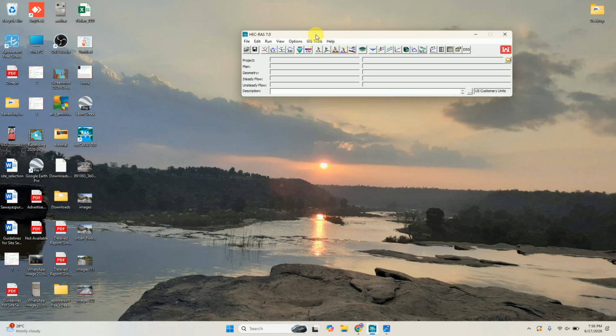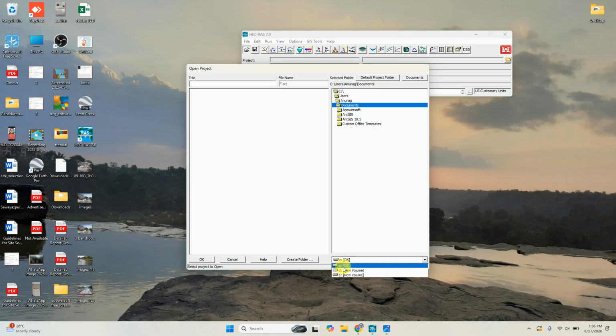Before 6.7, you will not find this feature in HEC-RAS, but currently, after 6.7, it supports the pipe or stormwater network. HEC-RAS allows you to model the urban system with a stormwater network as well. In 7.0, it is more convenient and more flexible to use the pipe network. Here I am going to tell you how you can apply this drainage network, and you will find the impact of the drainage network in inundation mitigation.